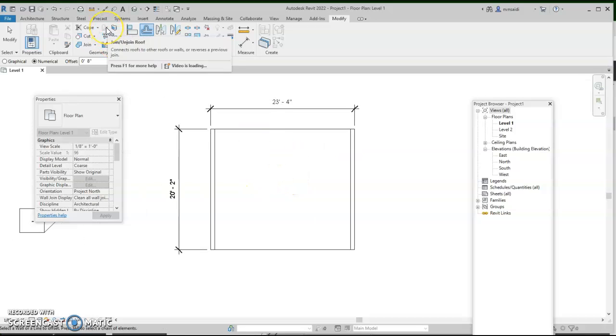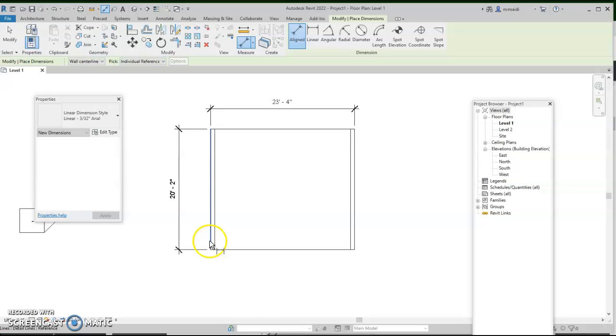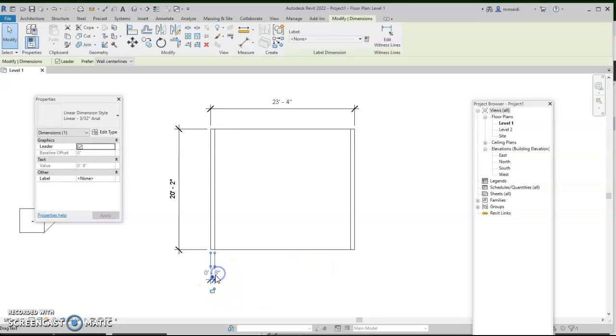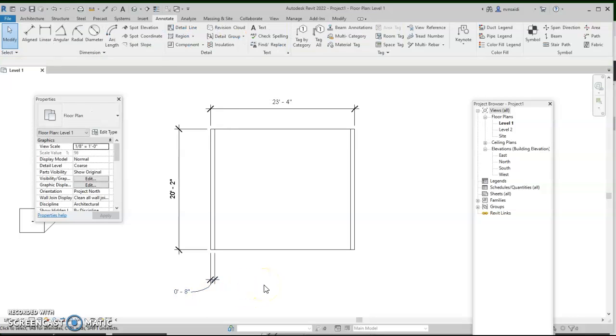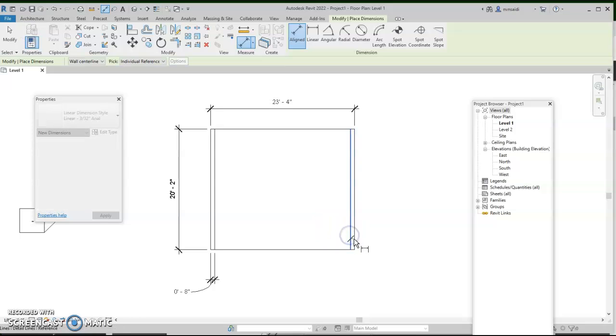8 inches. Let's double check on that. So I'm going to go to Annotate, Aligned, pick this line and that line, come on out here, and I see 8. Hit Escape. I pick, hit Escape again. I pick that line. You see that dot? Take that dot, yank it out. You can yank it down below or out this way. That tells me 8 inches. It's using the architectural system of dimensioning. Let's do it one more time on this wall. This one and this one. Pull it out. It says you wanted a line. Yes, I do. Click this line. Pull it out. I'm doing okay.